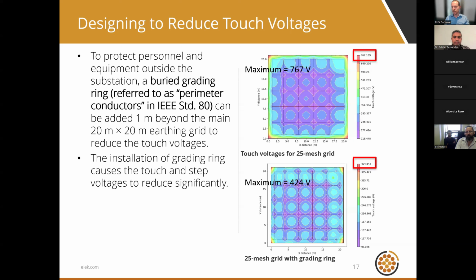Another reason is that this is the place where surface voltages drop off the most as you move away from the earthing system. So you've got somebody on the outside of the earthing system, perhaps outside the fence. Now the fence is very often connected to the earthing system, so it's at GPR potential. And somebody is standing outside the fence. Very often that could be someone in the public, and they could experience very high touch voltages during a fault condition as caused by the earthing system.